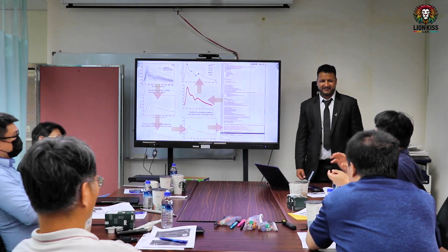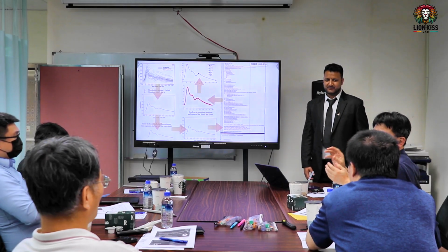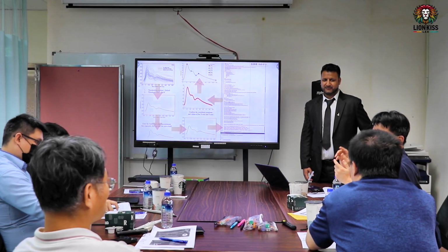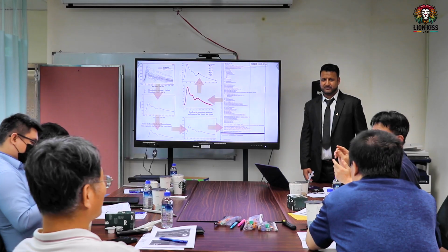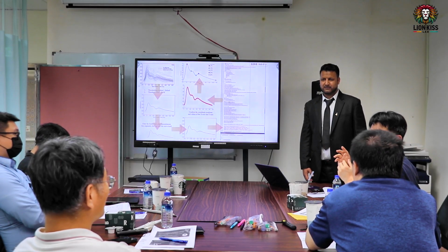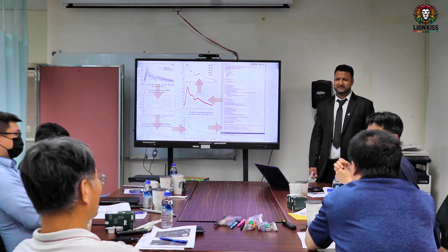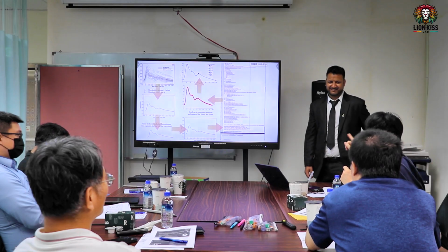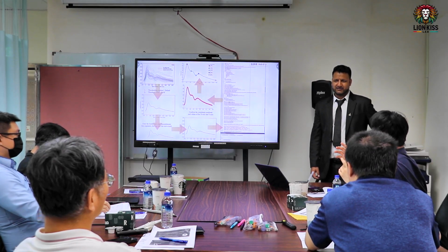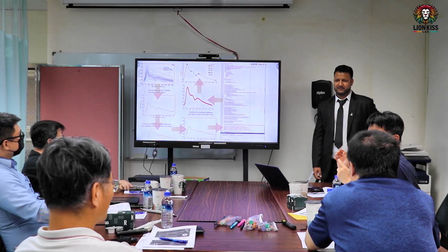Professor Hong asked about the laminar and the turbulence model. This depends on the Reynolds number, but in general, you use laminar flow when the blood vessel diameter is less than 2 millimeters. It depends on the size of the vessel. In some cases the diameter is larger than this, but laminar flow is still appropriate.